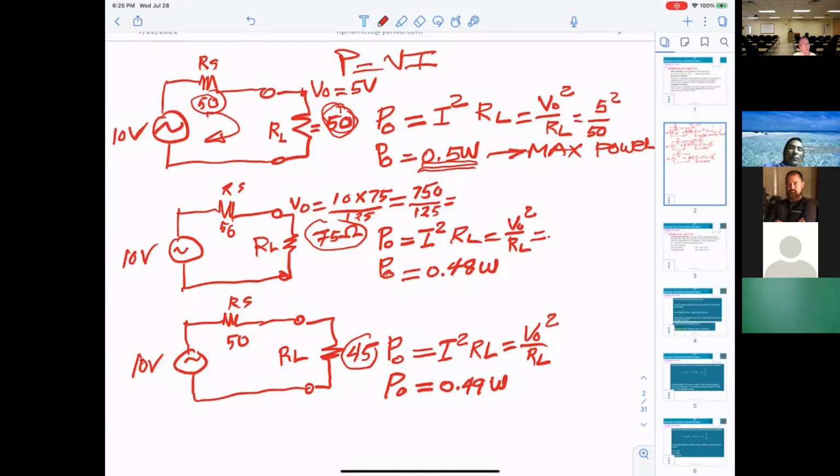With the CE amplifier, if you want more gain, you use the CE amplifier. However, for the CB and the CC amplifier, the gain is almost equal to 1. That means basically whatever comes in, comes out the same. They don't have any more gain.